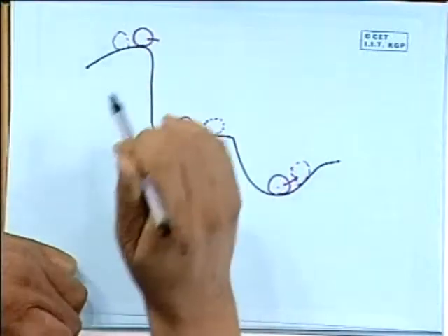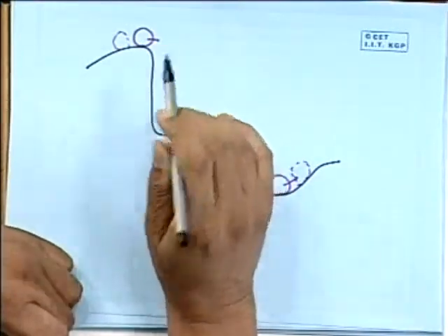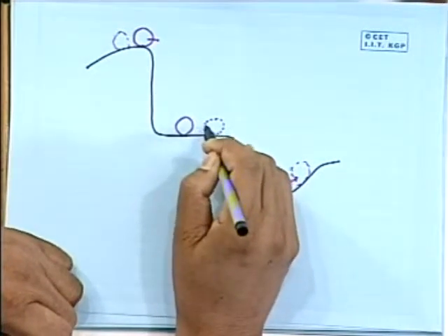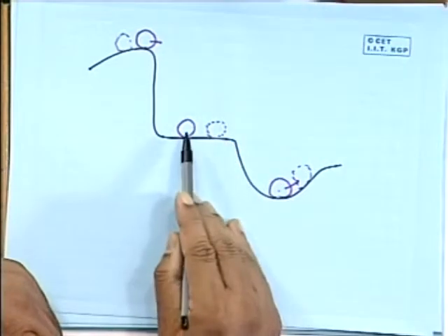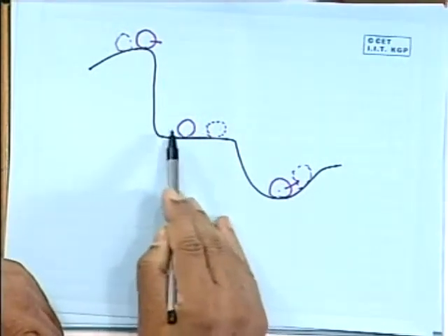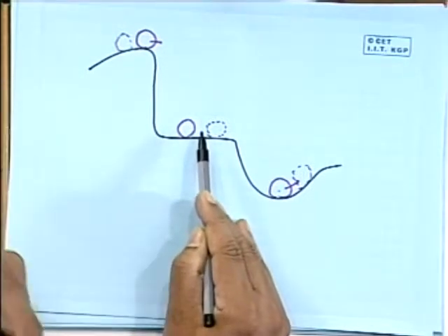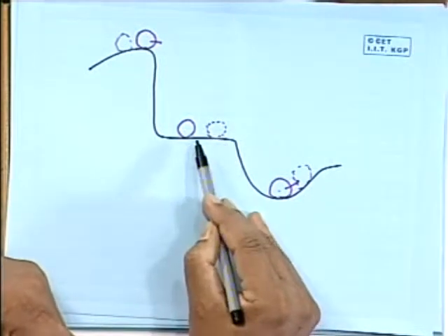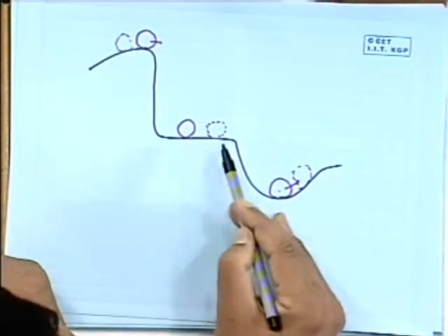Now this is the concept of stability, which basically means that the ball was here as it is. Now I try to move it from its state of equilibrium by giving some kind of external disturbance from outside. Somebody has pushed it, say by hand, and then that push has been withdrawn, I removed my hand. Now I want to know how that system would behave. Will it come back to its original state of equilibrium? Will it stay in the disturbed state of equilibrium, or will it deviate further from the disturbed state of equilibrium? So there are three ways it can behave, and these three represent what is called its stability property.